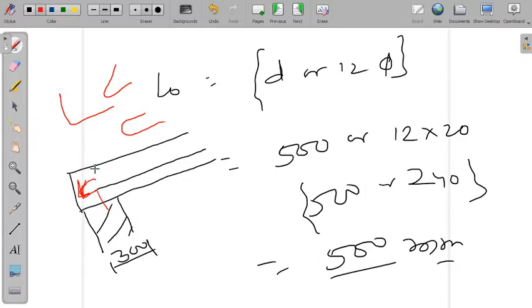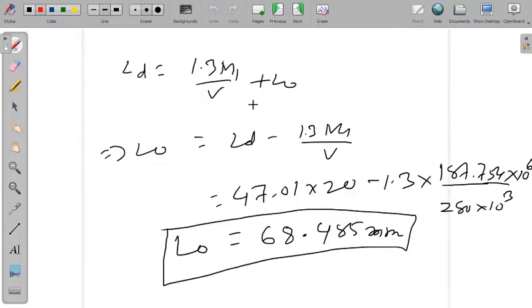Okay, so this is how we need to check that whatever we do by design, the anchorage length, that is the additional length, and the development length, is satisfied or not. We have to check development length for this type of problem. For any problem we are doing, we have to check that proper development length is provided, so that proper bonding will develop. Now since we are providing L0 as 100, as I said, I can provide this.